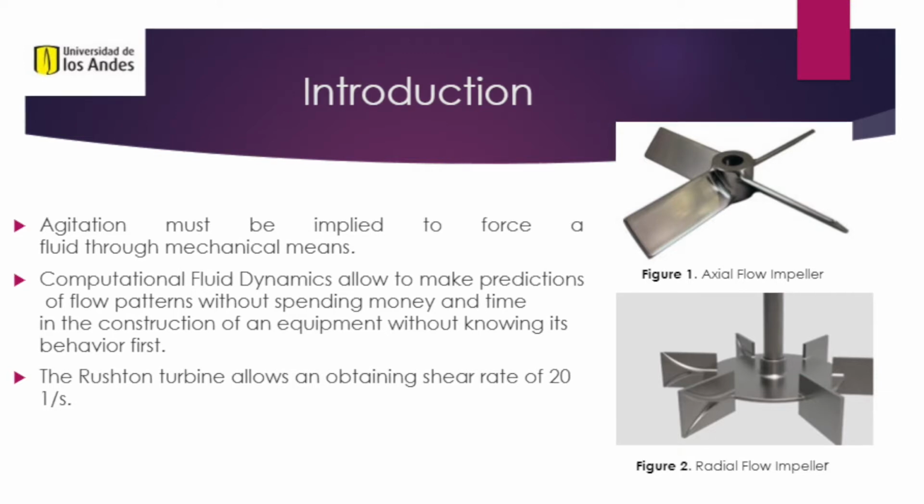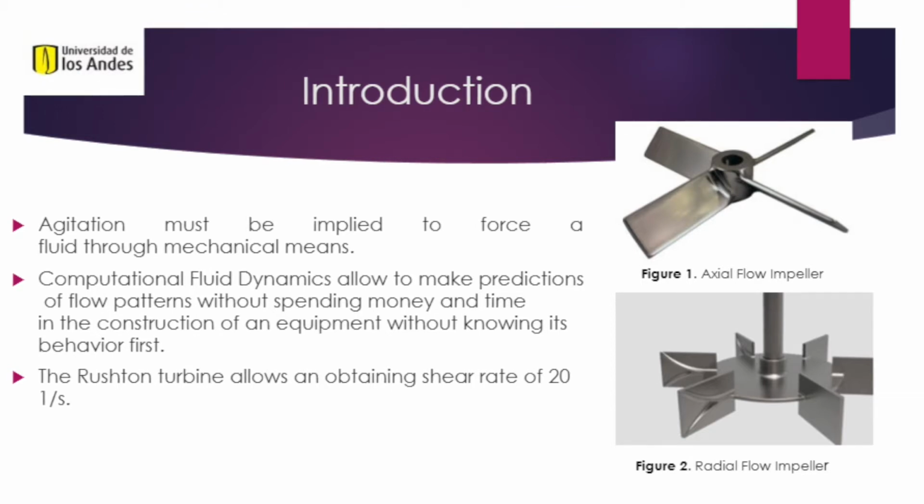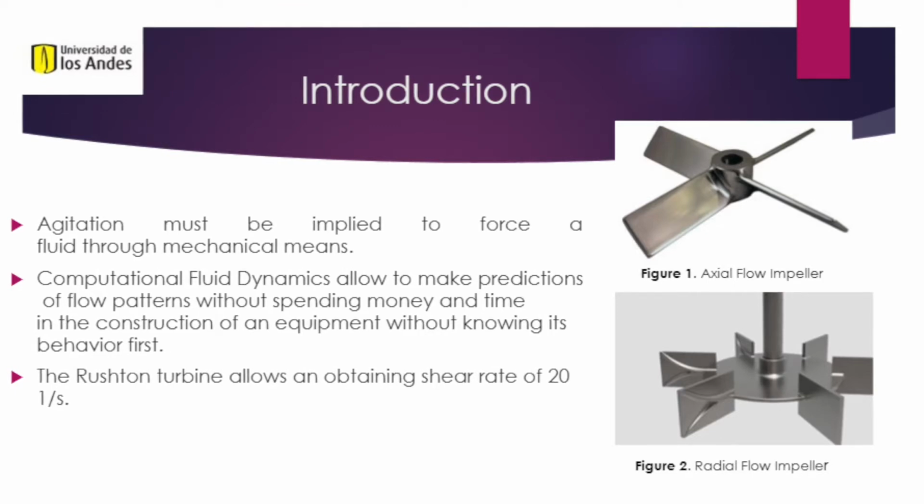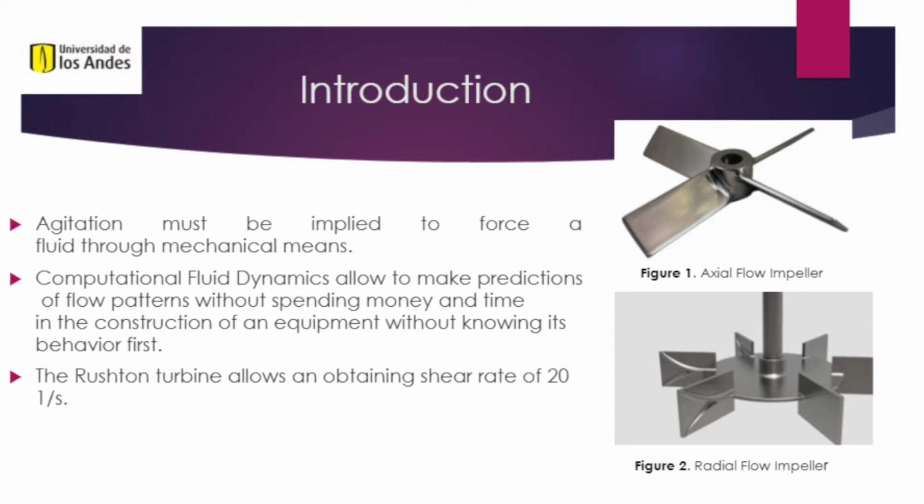The success of this process depends on the geometry and therefore on the design of the impeller used. For many years, the design was based on the power required, the cut that is made in the fluid, the pumping, and the time of mixing and flow patterns. This information was taken with experimental data. Nowadays, computational fluid dynamics allow us to make predictions of flow patterns without spending money and time in the construction of an equipment without knowing its behavior first.